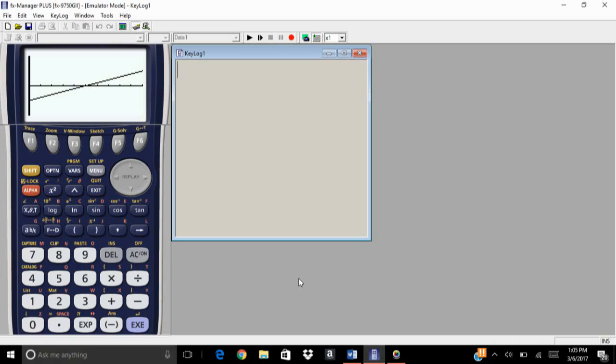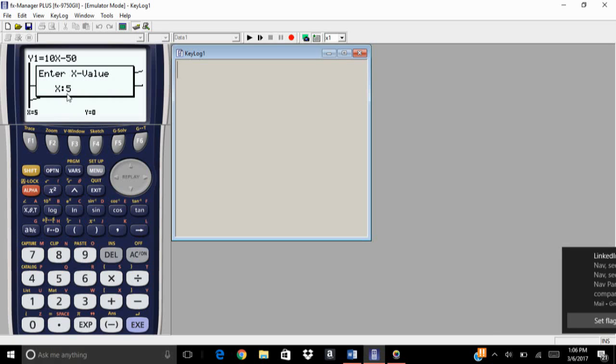In the calculator we get this graph, so we have to locate this point. At what point is this shear force diagram 0, and at a distance x equal to 2, what is the shear force value? So for that we have to click on shift trace. Okay, trace, and I'm just going to enter one number like 5. Then it takes that value 5 as x and calculates the value of y.